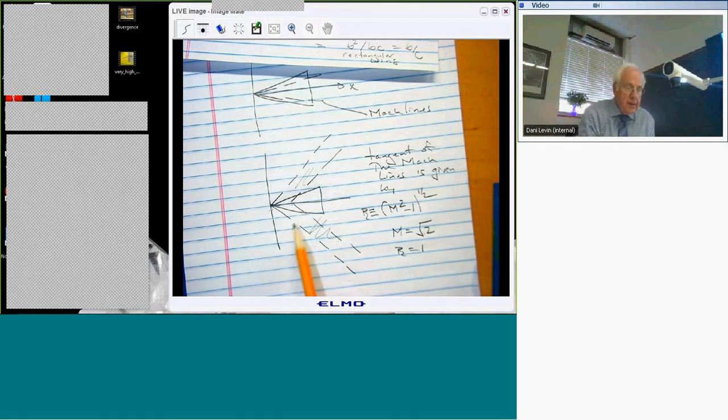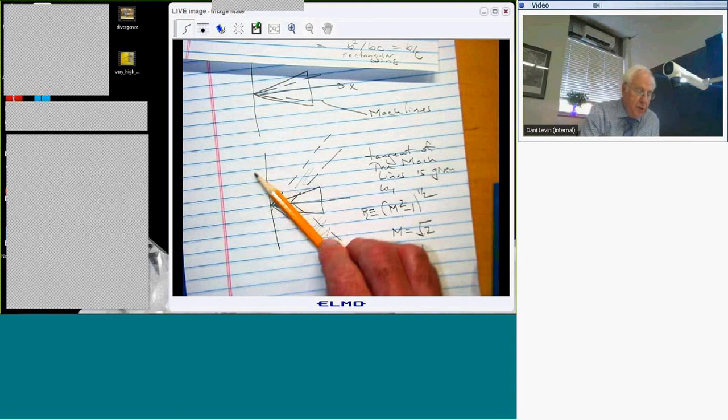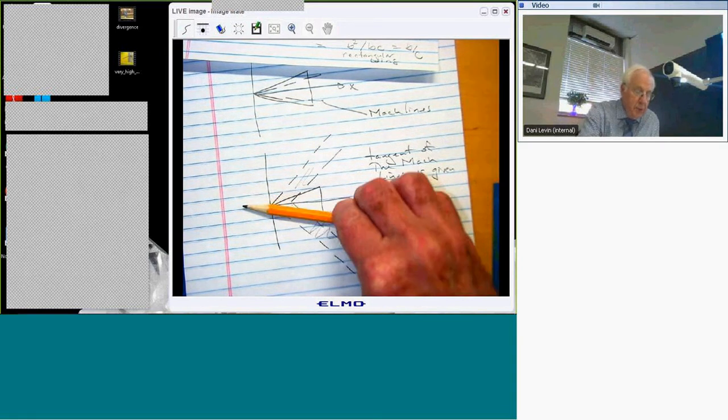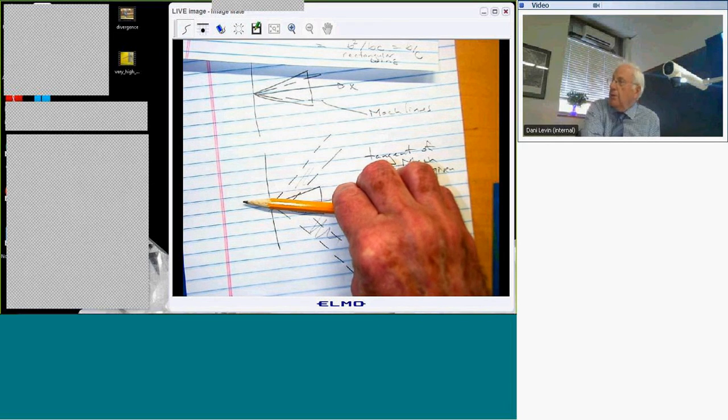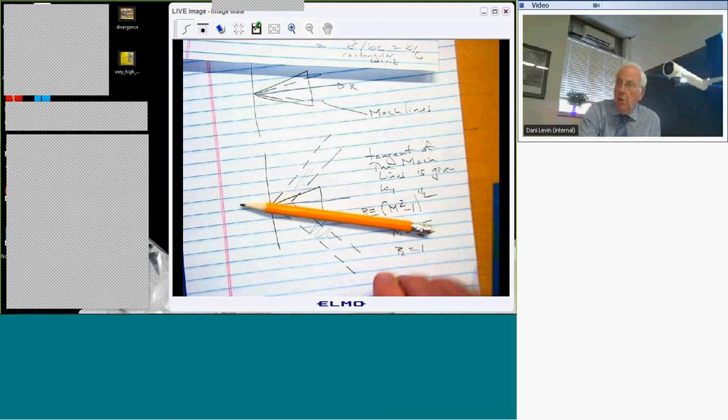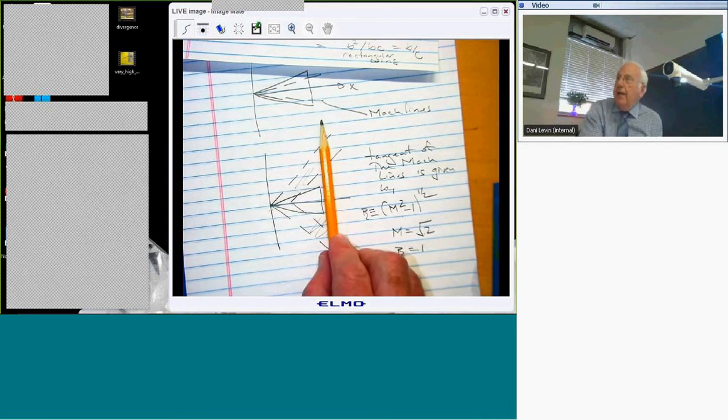So in this case, this is not a supersonic leading edge, right? Because the flow off the wing is disturbed. So when I say I have a supersonic leading edge, I mean I'm raising the Mach number high enough so that this line moves such that it's within the wing itself, and therefore there's no portion of the flow off the wing that's disturbed ahead of the trailing edge.